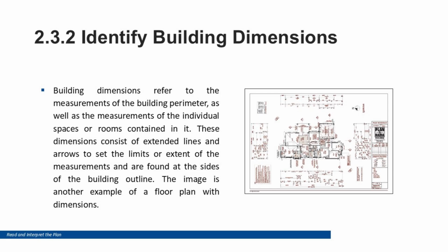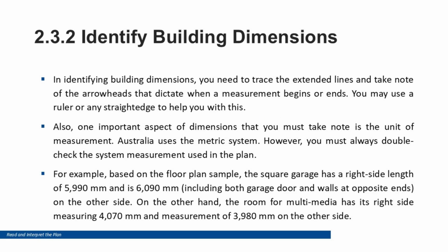Understanding how to scale drawings is also essential. Most plans are drawn at 1:100 or 1:50 scale, but detailed sections may be 1:20 or 1:10. Never assume, always check the scale noted in the title block. When using CAD drawings, you may rely on digital measurements, but printed plans must always be checked with a scale ruler. Accurate measurement ensures correct installation, ordering of materials, and verification of on-site workmanship.